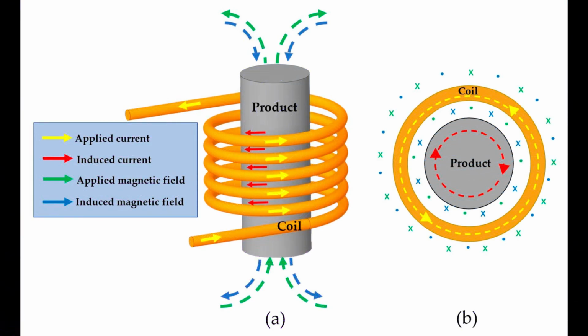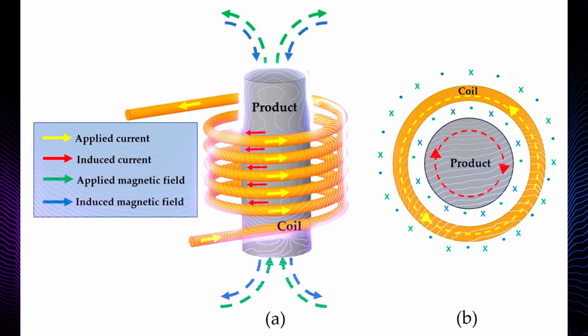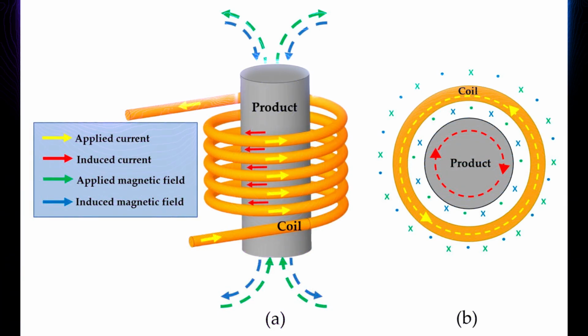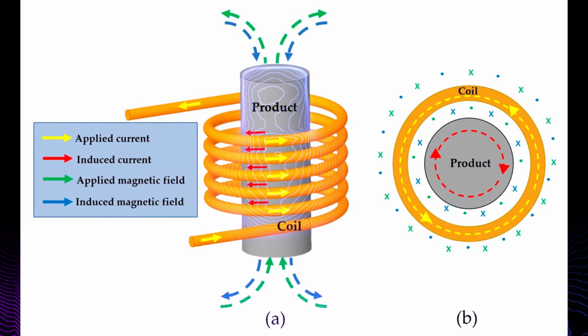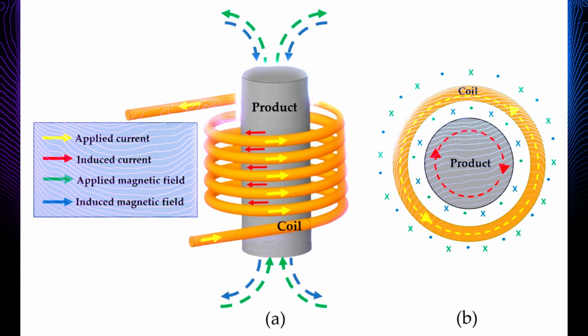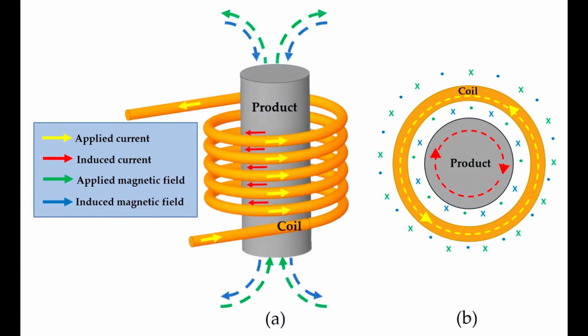An increase of frequency will cause the magnetic lines of flux to cut the conductors at a faster rate, and thus will produce a higher induced voltage or more inductive reactance.